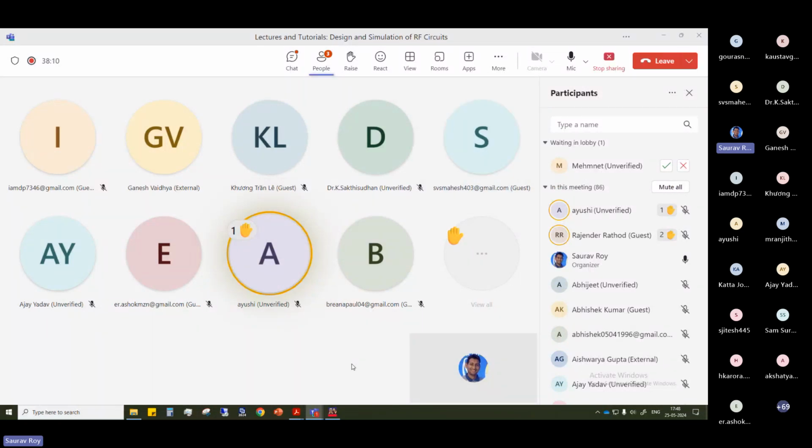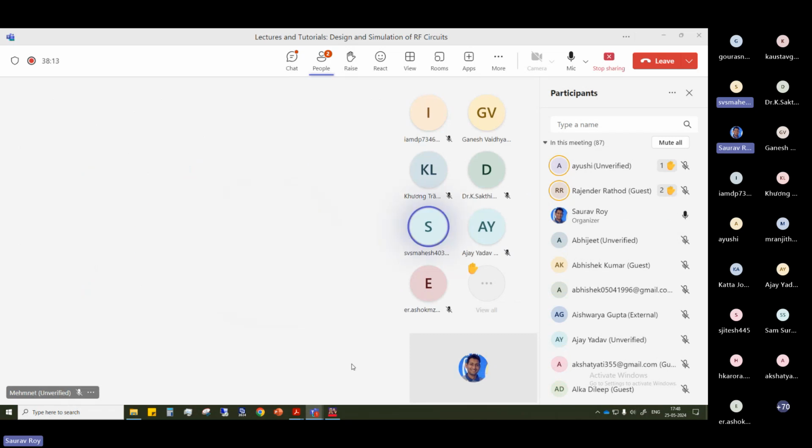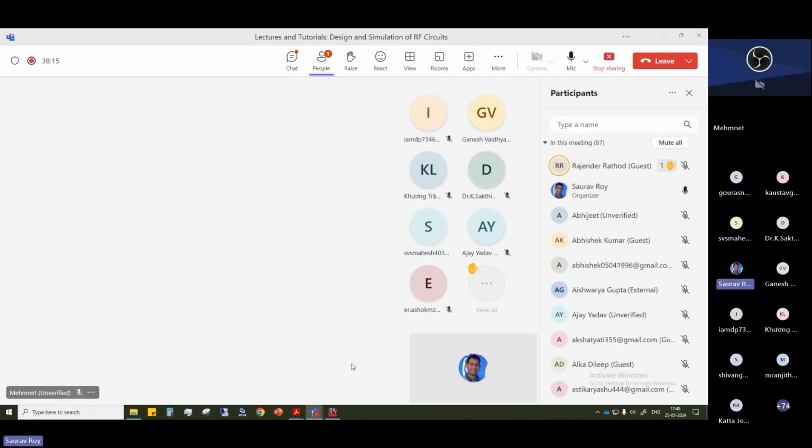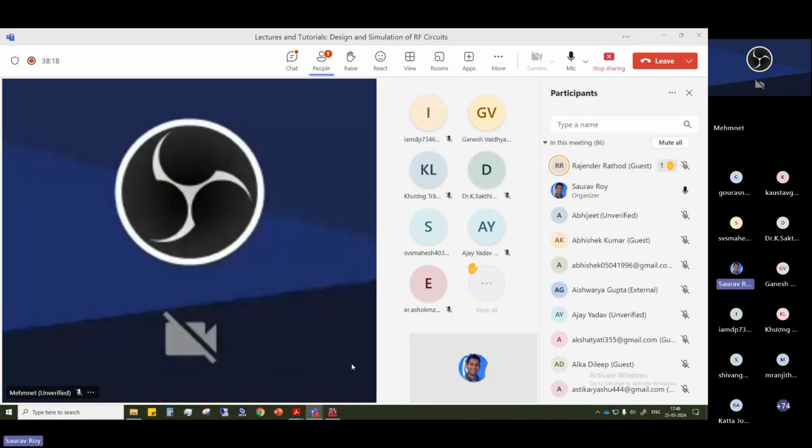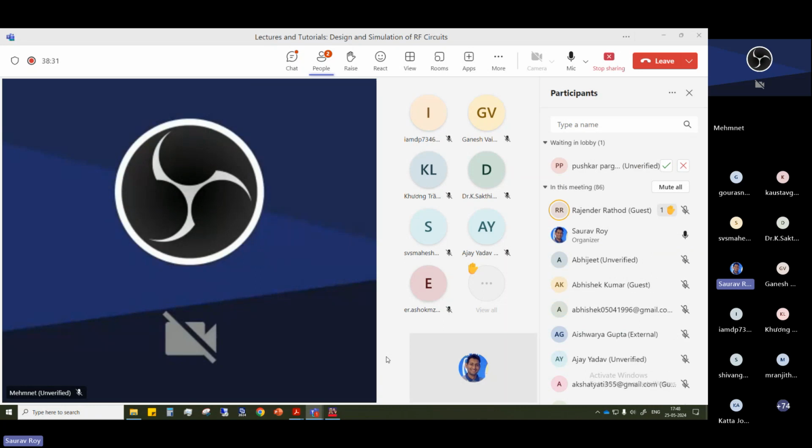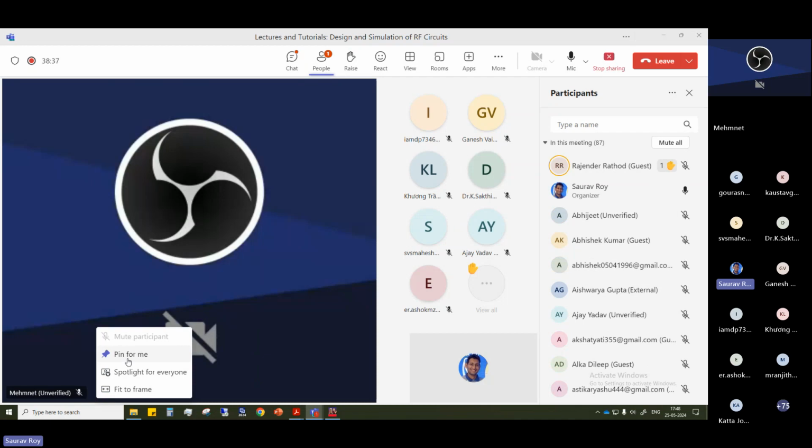Another section is noise figure. If you have a matching section added or some other network added, you might reduce the noise, or you can increase the noise there. So you must have a trade-off, like how much maximum amplification you can do, and the noise figure you also have to minimize. So we'll look into matching, maximum power delivery or maximum amplification possible out of the amplifier, as well as noise figure.